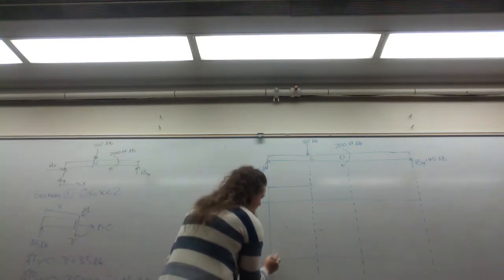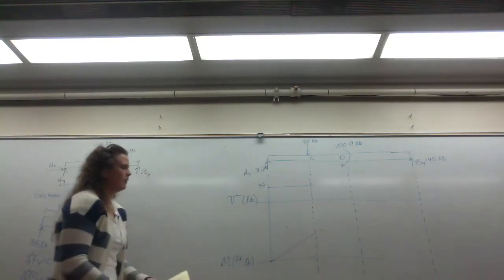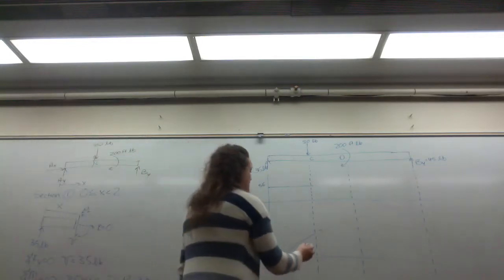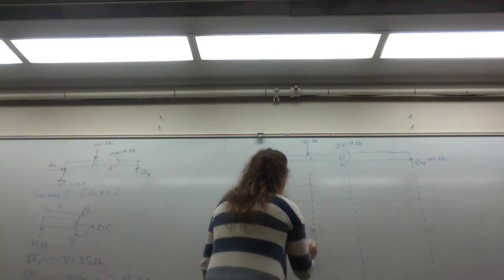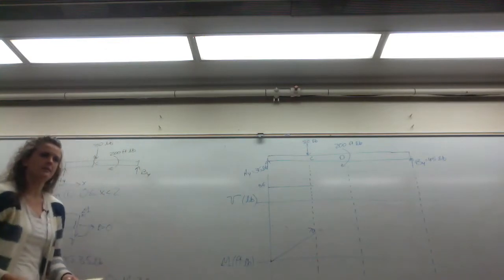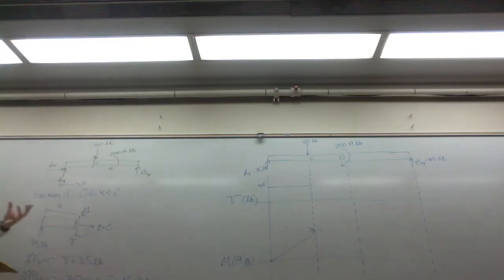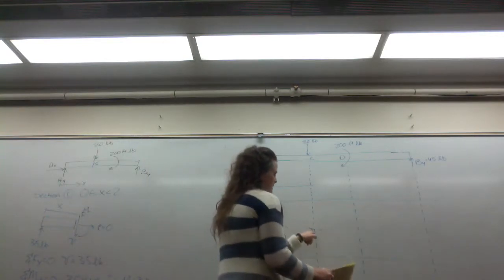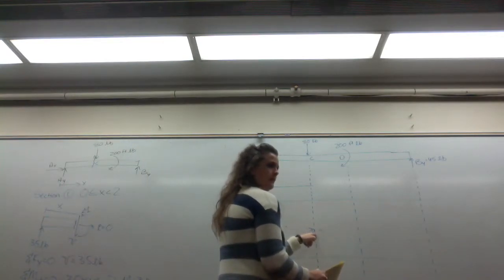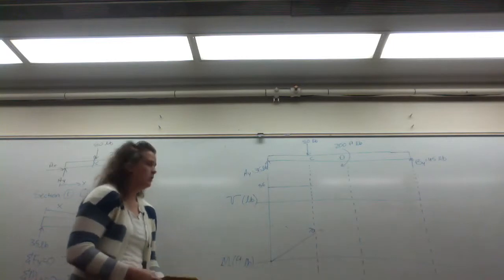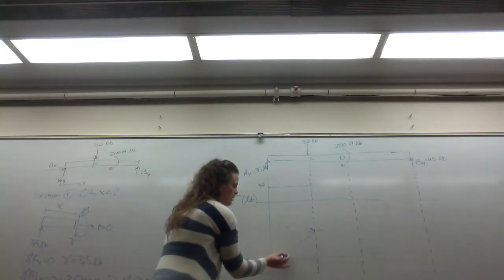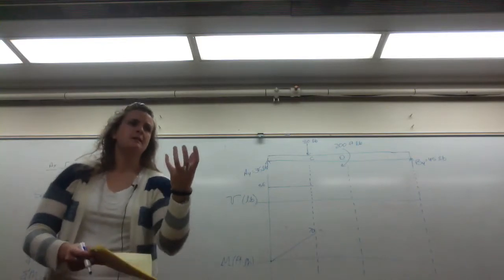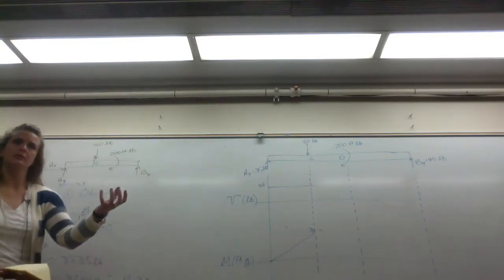But as x progresses, our bending moment increases until we are at x equals 2, and we know it's 70 foot-pounds. So Keenan, if you had plugged in x equals 2, you would only find this value. But here, we can look on our graph and immediately pull out what our bending moment is between x equals 0 and 2.